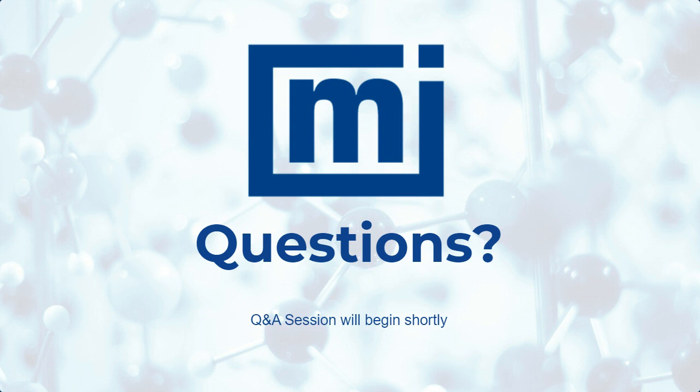If we wanted to differentiate between caking and agglomeration, is there a strategy that we can use to make that differentiation? Yeah, I guess agglomeration really is caking over short scales, so short range caking. Fundamentally, there is no difference. But when we see this in the sample, we have locally caked regions, the agglomerates, and then widespread caking, which is what we see in here. So I would expect to see differences.